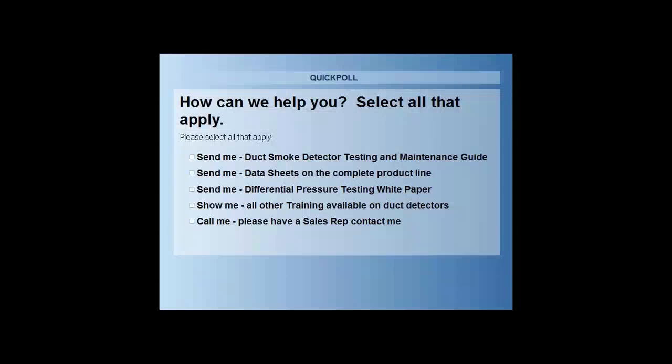What you always want to ensure is that your sampling tube goes at least 2/3 of the way across the ductwork if it doesn't go all the way through the other side. And you want to make sure that the holes have an even distribution across the width of the duct. As long as you have that, you're not violating any sort of listing. Okay, good.